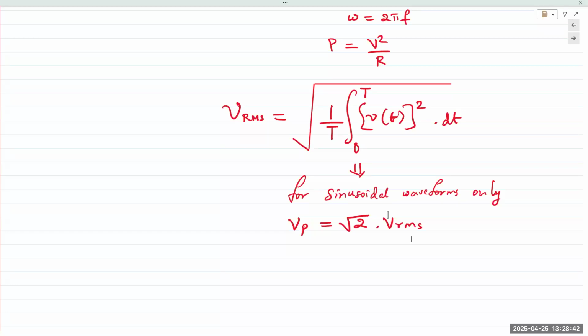That's just peak to peak, because it came from the sinusoidal waveform, but does not have a defined name for it. It's just AC. So the question being asked is for ripple, for a ripple voltage, how do we measure it or how do we define it? We define it either in peak to peak, or RMS.